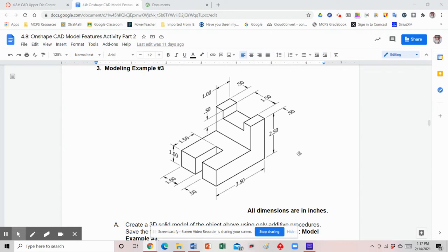So that means if I'm going to do it from the top view, the dimensions that I need to know then are the depth dimension, okay, so from the front edge to the back, and then the width dimension. So the overall width, if you notice that they don't give us an overall size of it, what they do is they break it up into little parts here. So if you notice, it's half from this left edge to here, and then 1.5 in the middle, and then another half. So if we add that together, that's going to give us a width of 2.5. Okay, so that is where I'm going to start.